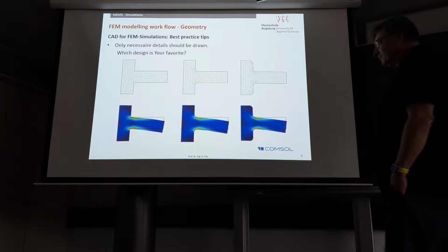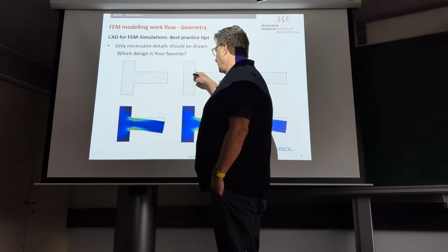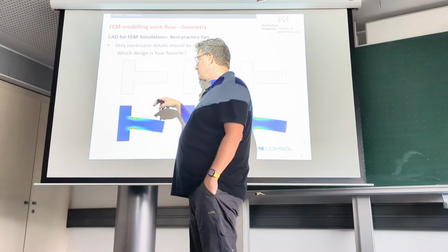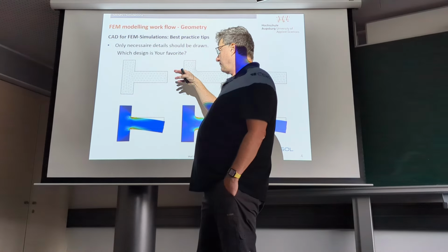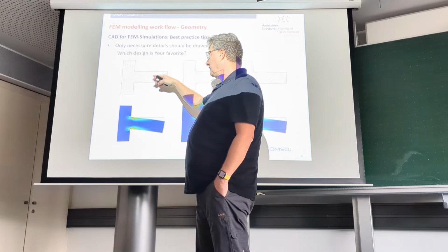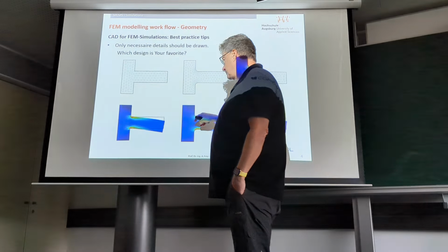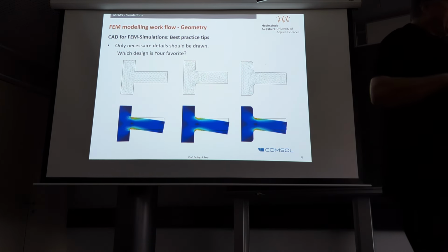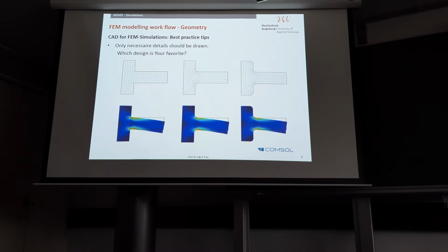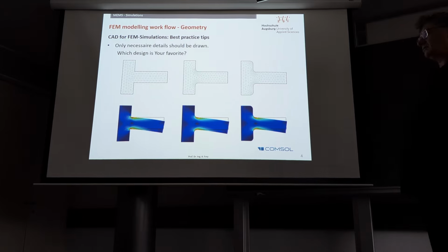For that reason, neglecting that fillet to make a simpler geometry, and by having a simpler geometry getting fewer mesh elements, you would have a solution. You also get stress, but that is by nature meaningless. We discussed this topic, singularities arising in certain situations, today also in more detail. So definitely you cannot choose this geometry.